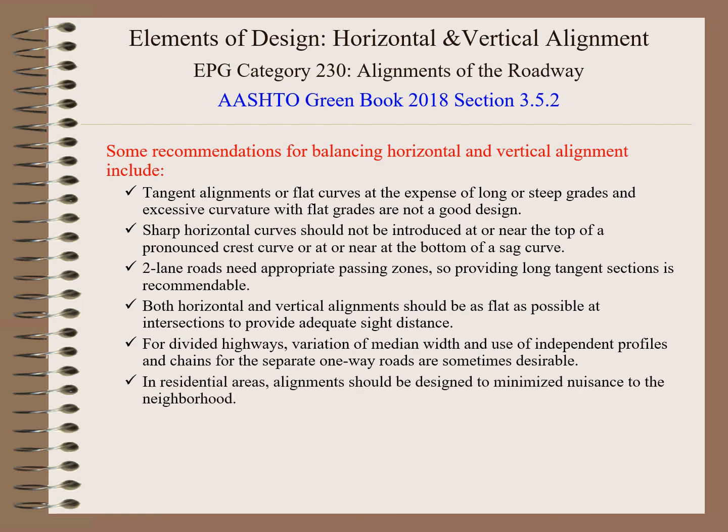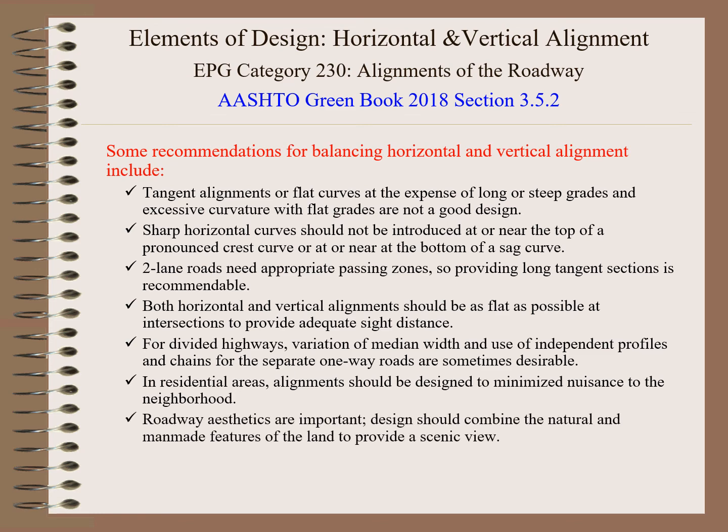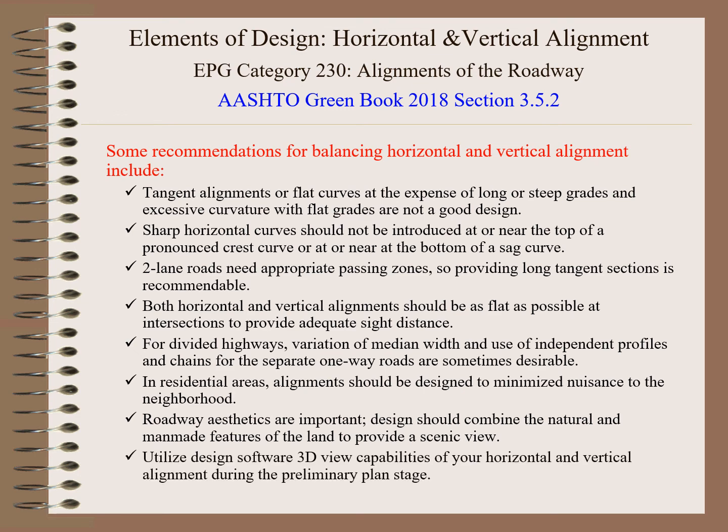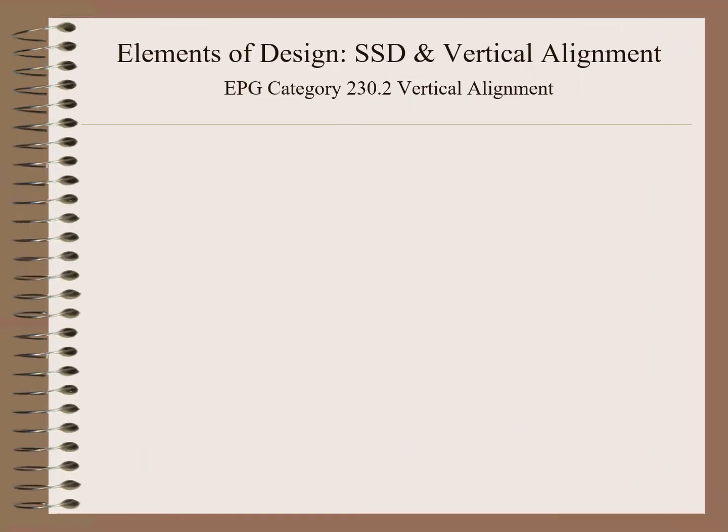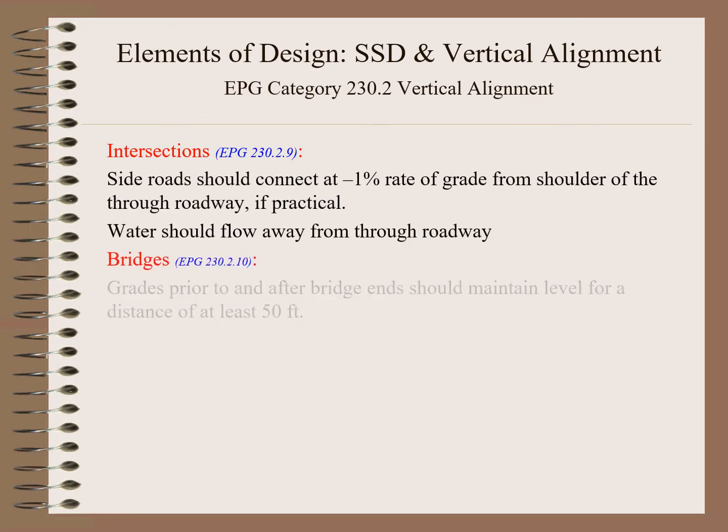In residential areas, alignments should be designed to minimize nuisance to the neighborhood. Roadway aesthetics are important. Design should combine the natural and man-made features of the land to provide a scenic view. Utilize design software 3D view capabilities of your horizontal and vertical alignments during the preliminary plan stage. When designing grades at intersections,